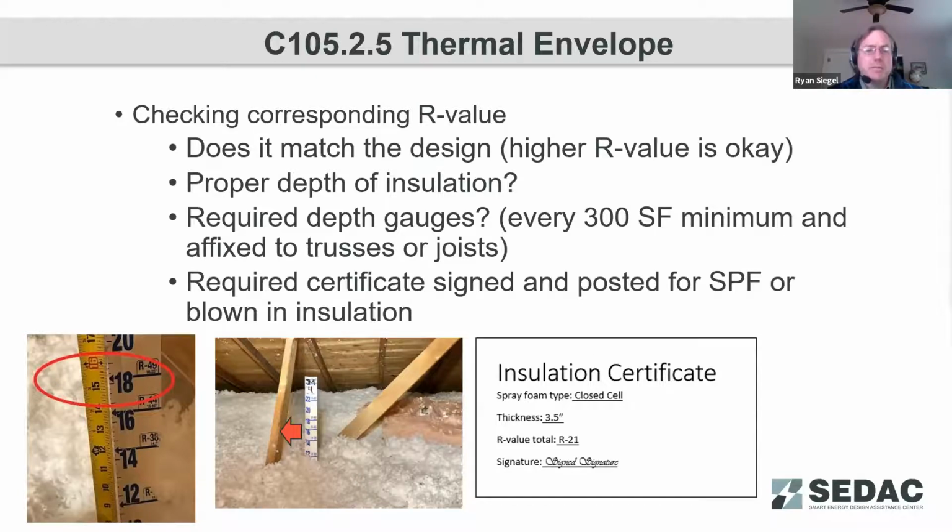This can provide some additional benefits over time as buildings may be changed or improved, and understanding what was there. And so if you see that it was originally applied to be 3.5 inches, and you go up into the attic and you find the insulation level is 5 inches, then you know that some additional insulation has been added over time, which can impact sizing for heating and cooling equipment.